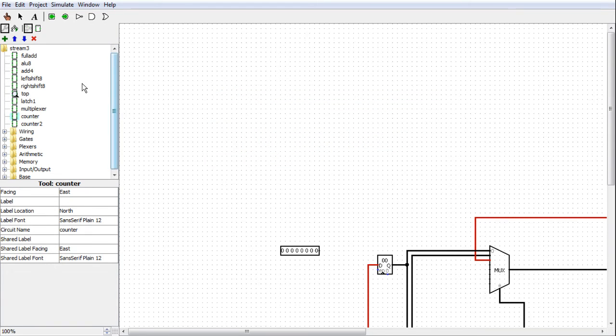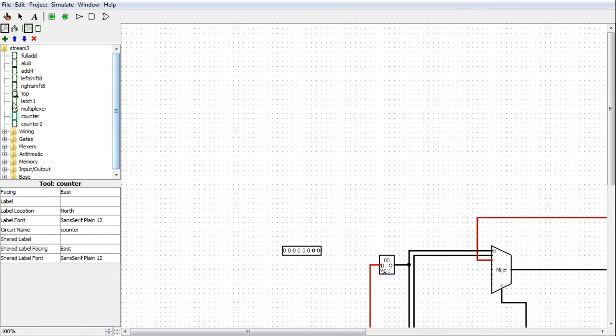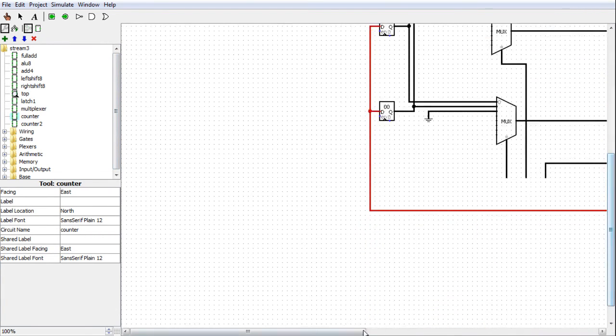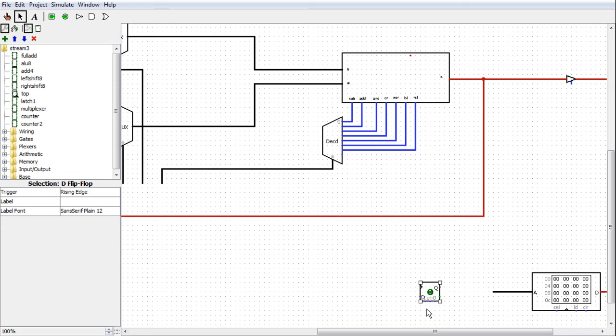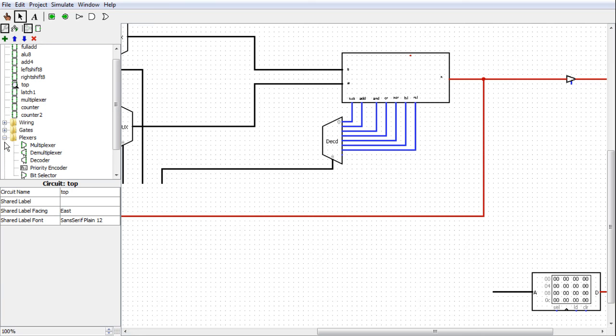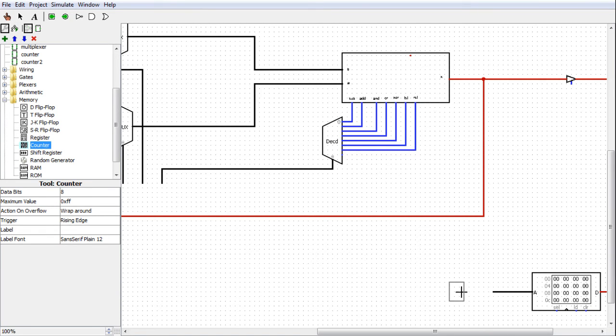All right, so we've got a counter register. We designed it. It works perfectly, no problems whatsoever. Now what we're going to do is import one of Logisim's, which has the exact same functionality, no difference whatsoever, of course. Yeah, counter. Here we go. So we've got our counter. It's got the Q and the not Q, and it's got data, count controller, and this thing here. This is the data load enable, which allows you to load into here.